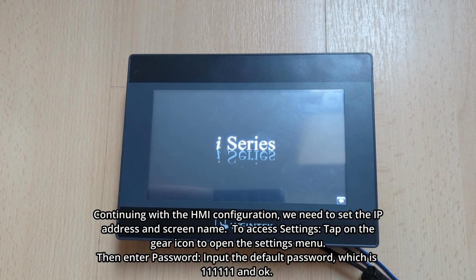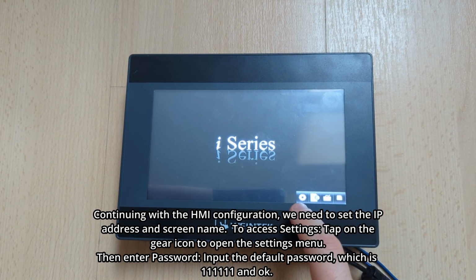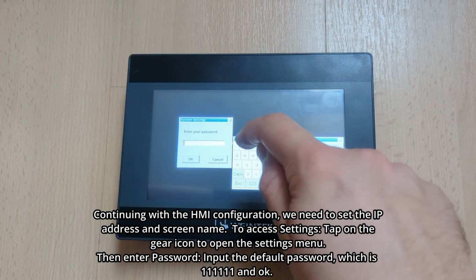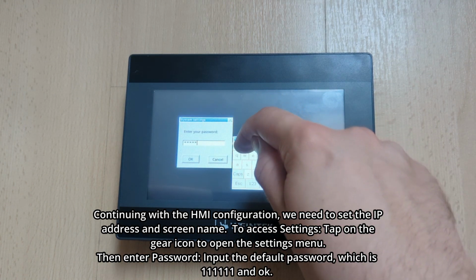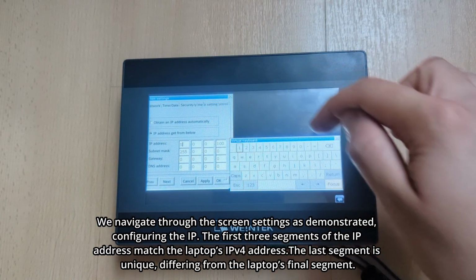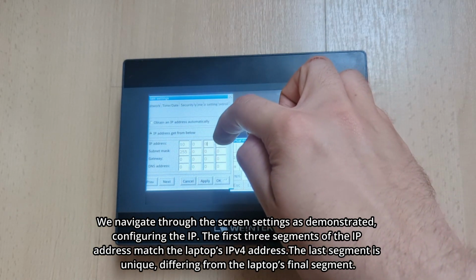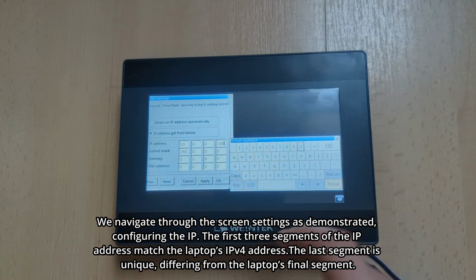Continuing with the HMI configuration, we need to set the IP address and screen name. To access settings, tap on the gear icon to open the settings menu. Then enter the password. Input the default password, which is 111111, and press OK. We navigate through the screen settings as demonstrated, configuring the IP. The first 3 segments of the IP address match the laptop's IPv4 address. The last segment is unique, differing from the laptop's final segment.